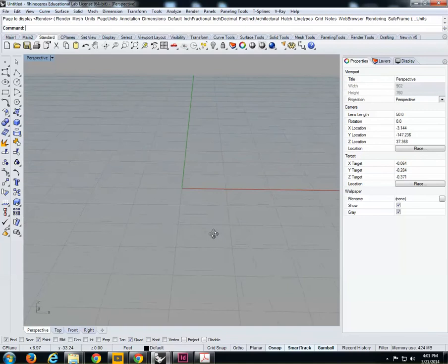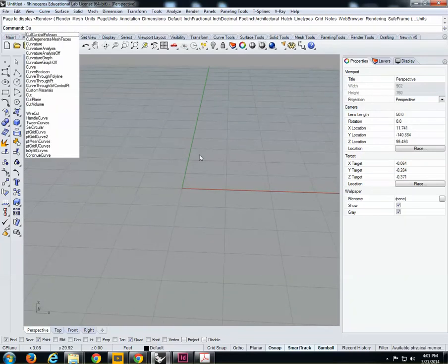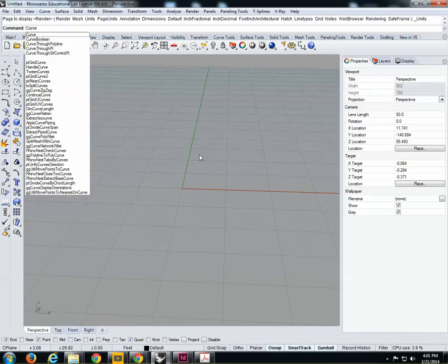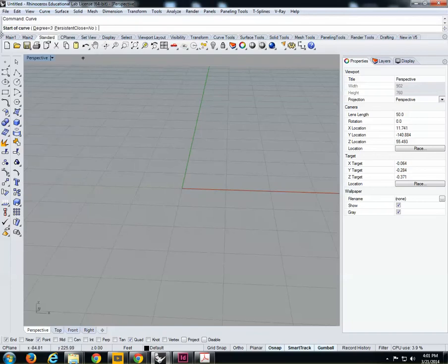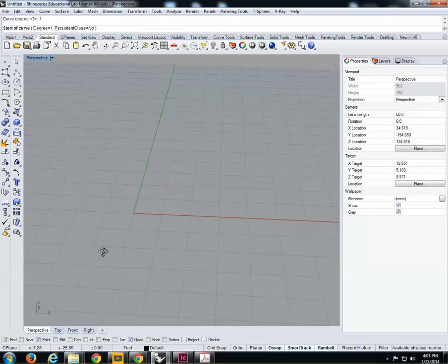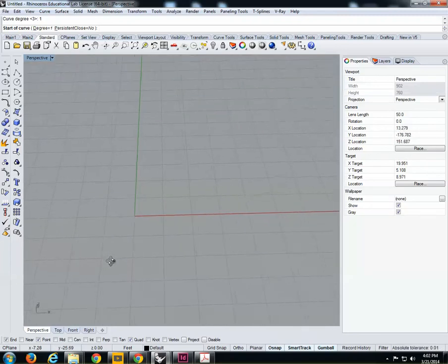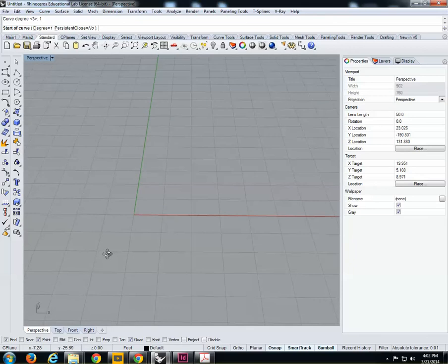Okay, number 2, we have to type curve with degree number 1. So we aim towards a polyline here with sharp edges. Curve, in the parentheses, I have to be very careful that I change the degree from 3, that is usually the default, to number 1. Enter. And I need to create a polyline, a rectangle that has 200 by 150 feet dimension.